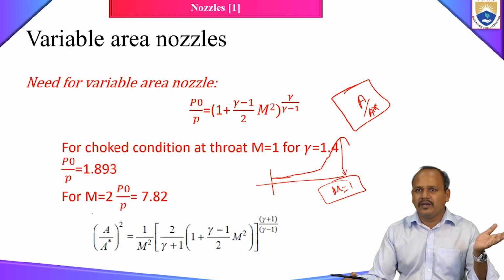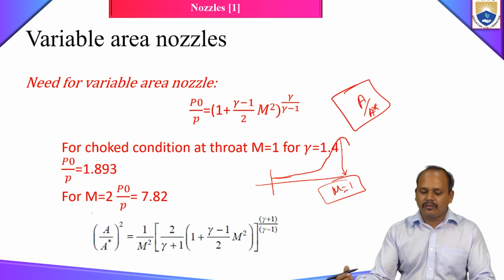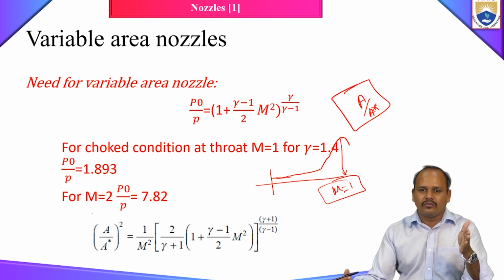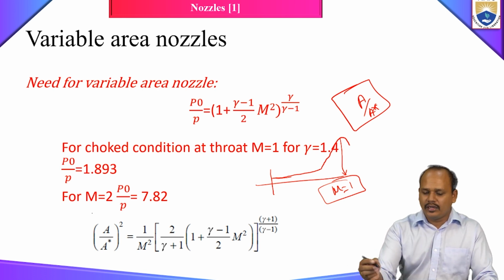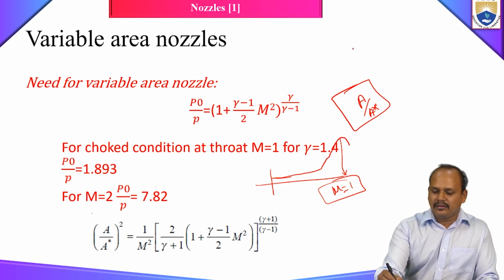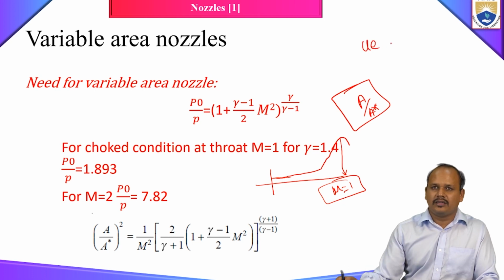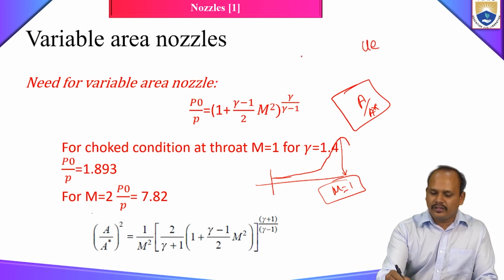Afterburner, right? We have already studied this in the first chapter. In the afterburner, after your flow comes out of your turbine, you can once again do combustion and increase the thrust generated, which depends on your exit velocity. Your exit velocity is a function of your flow temperature T0.